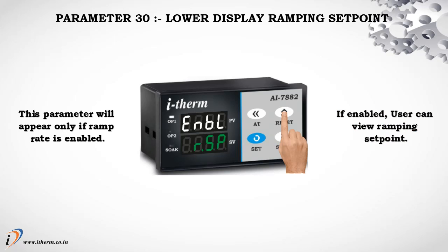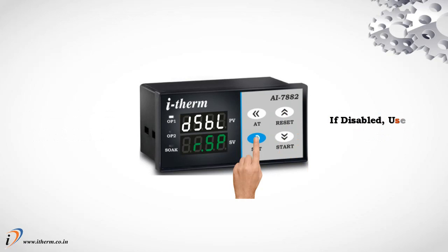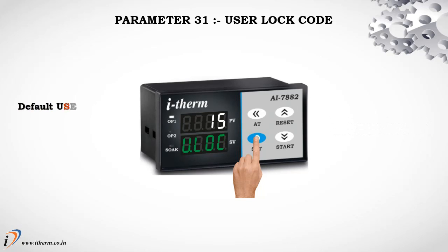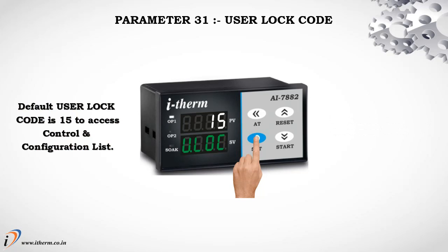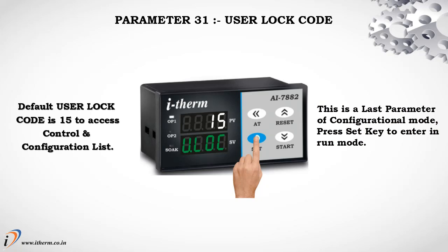If enabled, the user can view the ramping set point. If disabled, the user can view the target set point. Parameter 31, user lock code. The default user lock code is 15 to access the control and configuration list. This is the last parameter of configuration mode. Press the set key to enter run mode.